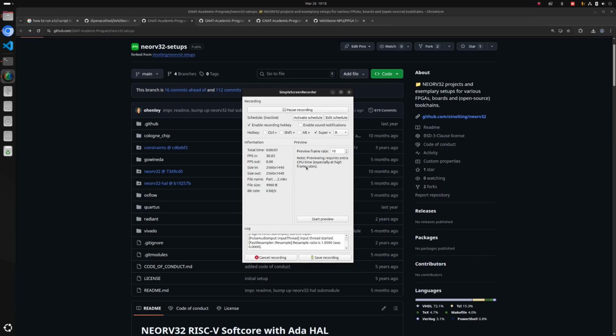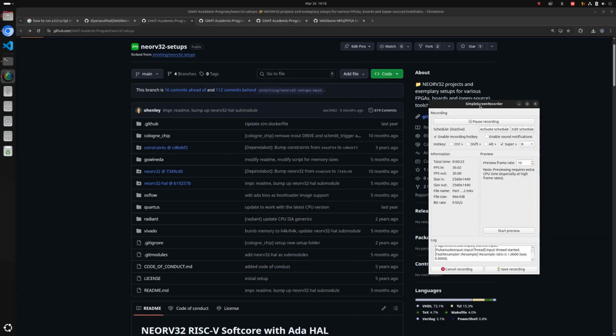Hello, this video will show you how to get the NEORV32 running on a Lattice ECP5U5MG85F evaluation board. We are going to use a specific fork of the NEORV32 RISC-V microprocessor, specifically one that is compatible with the Ada NEORV32 hardware abstraction layer. This is Mr. Olivier Henley's NEORV32 setups main fork.